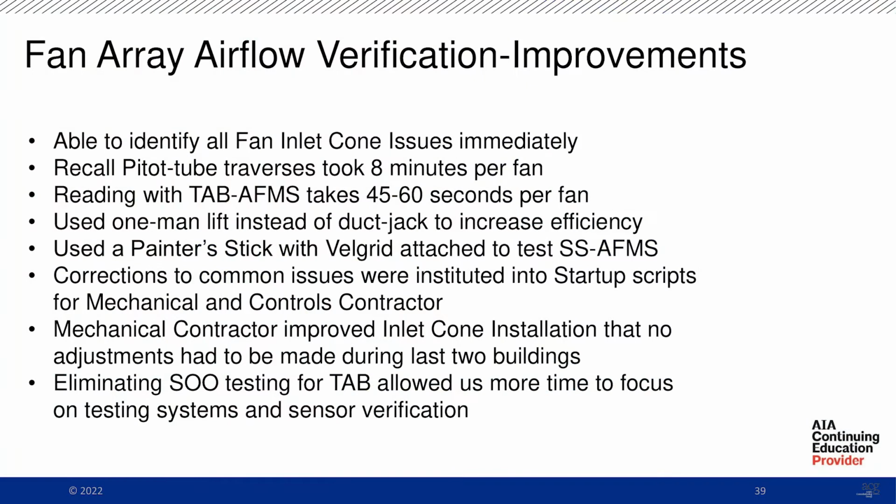With this change in TAB procedure, we were able to identify all the fan inlet cone issues immediately. When we were doing our pitot tube traverses, it took about 8 minutes per fan. When we changed to our new rig, it took about 45 to 60 seconds.